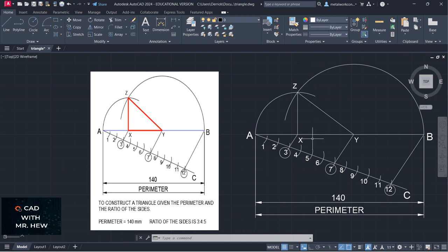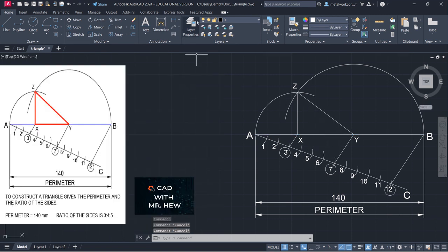All right, what we're going to do now, we're going to break the line XY. So we're going to go to the modify ribbon, and I'm going to break. Going to select the line, enter, and object snap is on. So right here will be the first breakpoint, enter. Going to select this object, see it's now a shorter line, press enter, and the breakpoint will be right here at this intersection. Enter. So when I click on the line, see, it's a different line. Before it was one line, now it's three lines.